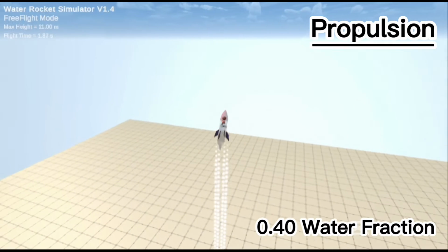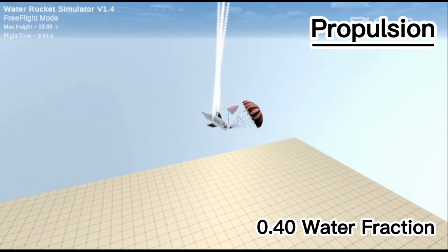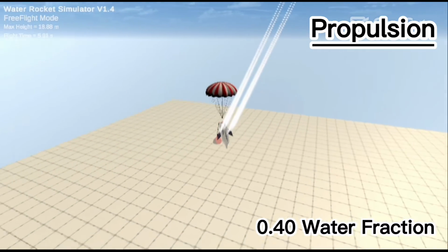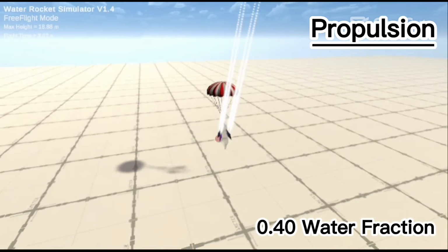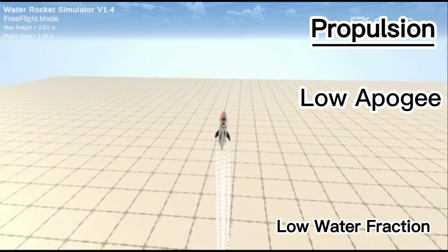Thrust produced by a water rocket is equal to the product of the difference in pressure of the compressed air and the atmospheric pressure with the area of the nozzle. To achieve max flight time, we need an optimum water fraction, usually around 40% as seen on screen, as this produces a large enough impulse. Impulse is the effect of force acting over time to change the momentum of an object.